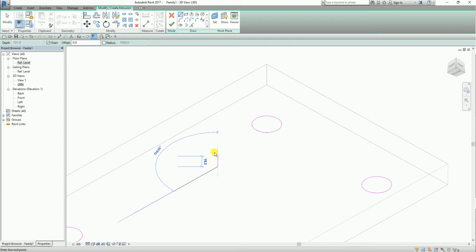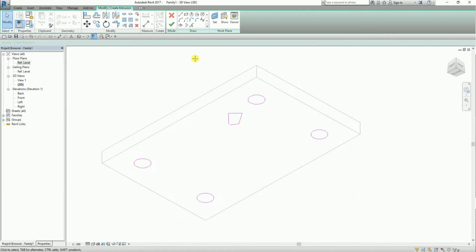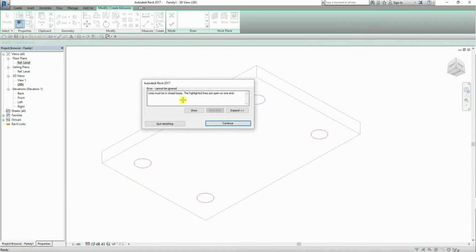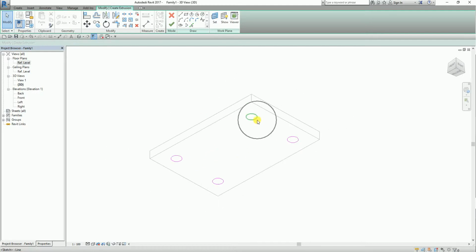What else? Make sure your sketch is closed. Let's say this one is not closed, right? So again, if I try to finish, I cannot. So it should be closed. Okay? So it should be closed, no intersection, no overlapping. Okay? Right. So after you create the sketch of your table leg, I'm now going to select here finish.